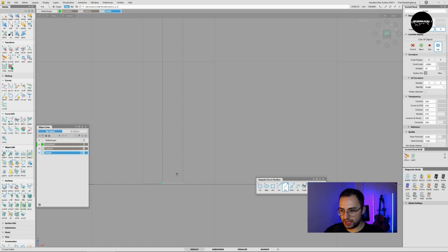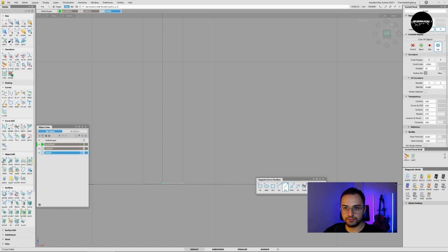But rather than that, how can we proceed? Yeah, we can change the pivot point of it by coming here, this tool, set pivot. I am holding Ctrl and left click. Since there is a key point over here, it snaps there.